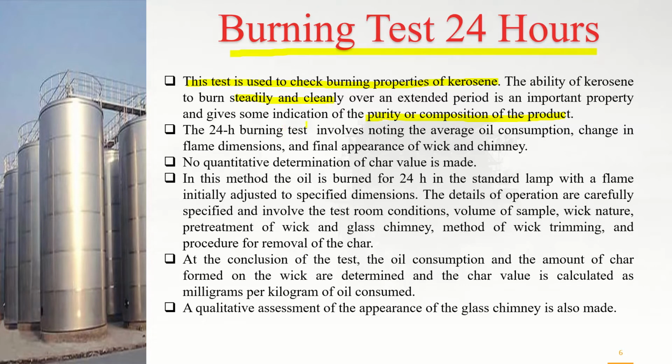There is nothing in the test. We burn the oil for 24 hours, and we will be seeing how its behavior and properties change after burning. Now, the 24-hour test involves noting the average oil consumption. These are certain things that we measure: oil consumption, change in flame dimensions, and appearance of wick and chimney.